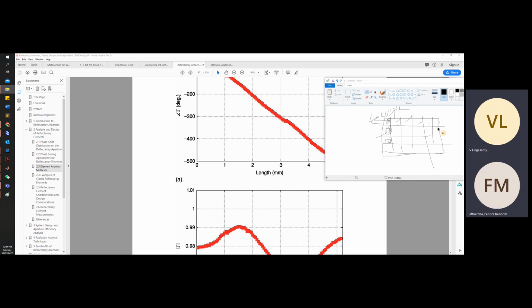That's why they are using a plane wave. A plane wave means it will not have any phase shift, it has uniform phase. You just impinge on this array and it reflects back. While reflecting back, it will have a phase shift, like minus 400 degrees, minus 300 degrees. If you analyze the phase diagram of this reflected signal, or reflected fields, you will see the phase. Whatever phase you found to be compensated at each location, the same thing will be reflected over here.